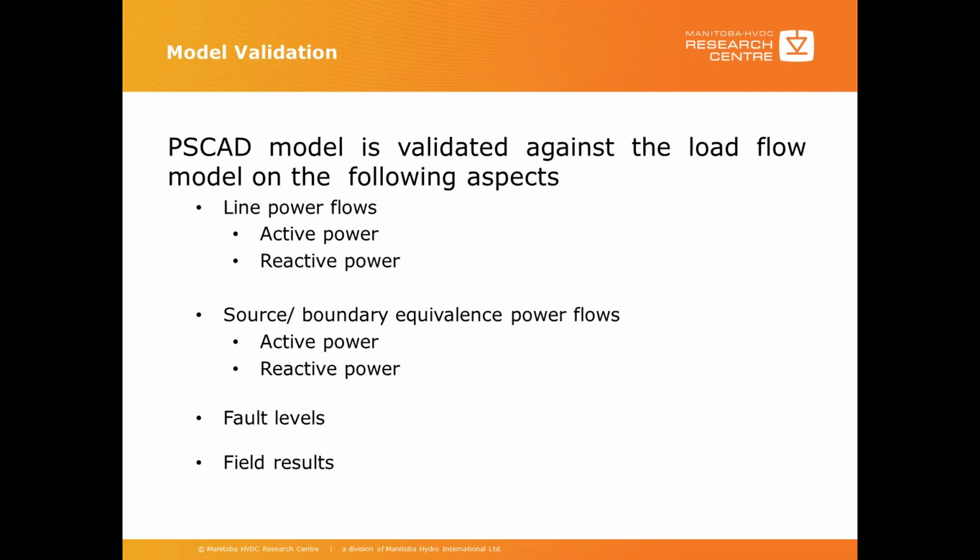Once the modeling is completed, the next step is to validate the model before performing the study. You can validate the model for load flow and fault level. The load flow and fault level can be generated from the other load flow programs such as PSCAD or from the actual field measurements. In next few slides, we'll show some of the examples of model validation.